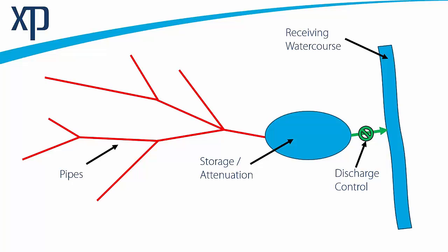Stormwater systems are more difficult. Rainfall presents us with a greater unknown, and it's that I'm going to be focusing on today. But just be aware that the principles of pipe design are the same, whether we're dealing with a storm or a foul water system. So these pipes that we can see here on the schematic, they could be a typical housing development or a retail park or an industrial estate or even a sports stadium or an airport or anything like that. Any sort of new pipe work that you're designing over a reasonable scale, a few hectares, can be done through MicroDrainage. So our first task is to design and size those pipes, and that's what I'm going to be talking about first.